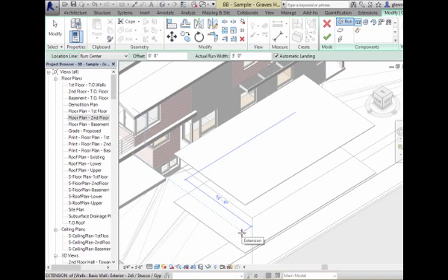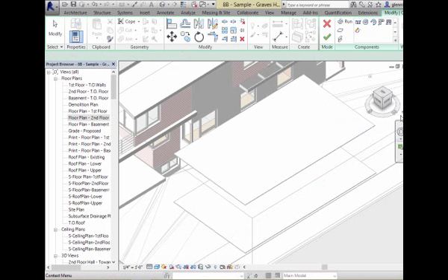So now that we've got our 8-inch stair, let's think about our issue here. We're suggesting a stair from the first floor to the second floor. No worries. It's telling us that that height is 9 feet. That's based on what the first floor and the second floor are in the building model. So 9 feet times 12, that's 108 inches. We're going to take that 108 inches. We've got this 8-inch stair. It's saying, if I took 108 and divided it by 8 into whole increments, I could actually get 14 different chunks in there if those chunks were 7 and a little more than a half inches. So it's 14 stairs.